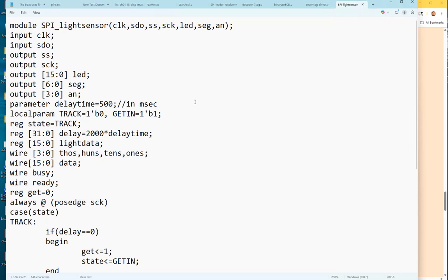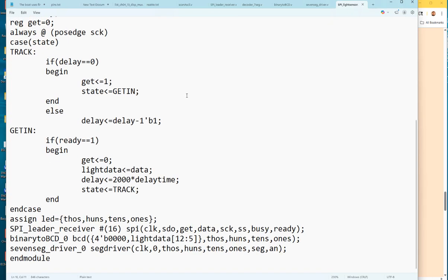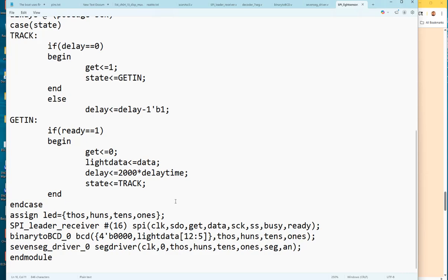And then we come back to the light sensor module, and you look at how these are getting instantiated. You can see the way the example instantiated everything here. They used a method that was not recommended. When we introduced this at the very beginning of the semester, we said do not really use the positional association method when we instantiate a sub module, because it assumes that everyone knows really well all the signal lines of all the sub modules. It does not have the dot something parenthesis something, right? It directly just shows all the signal lines in the parentheses.